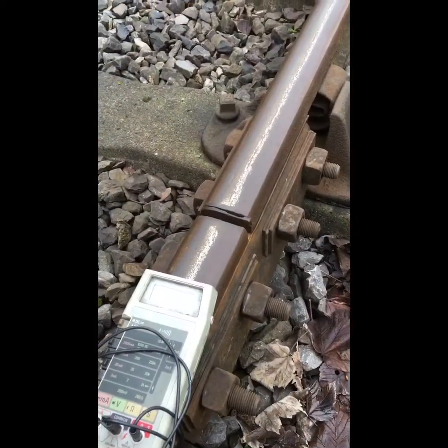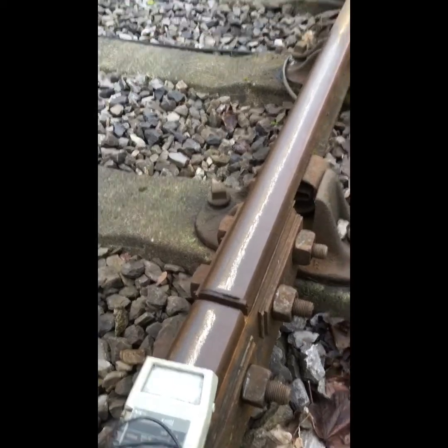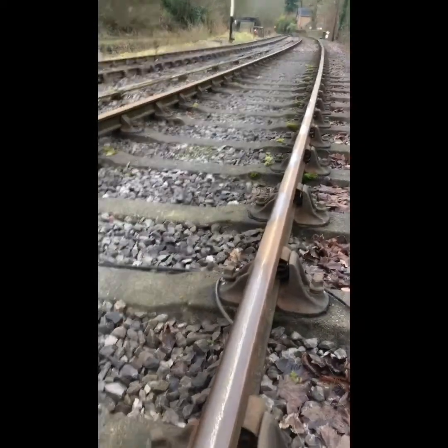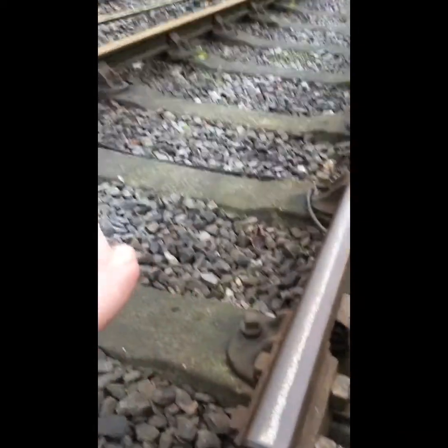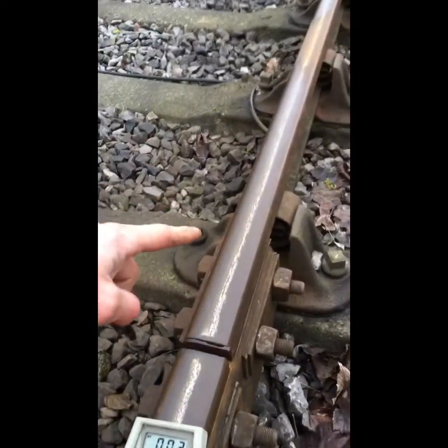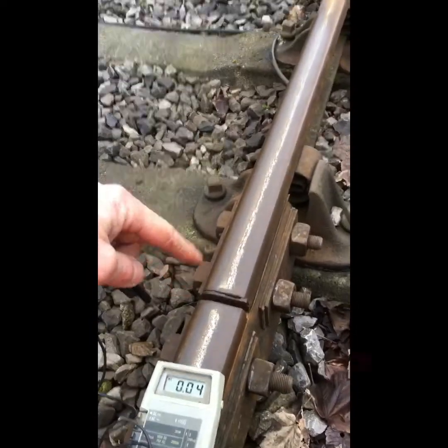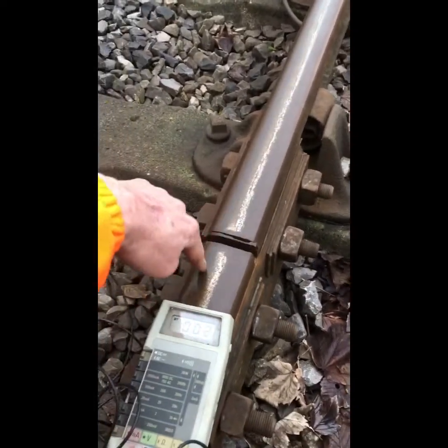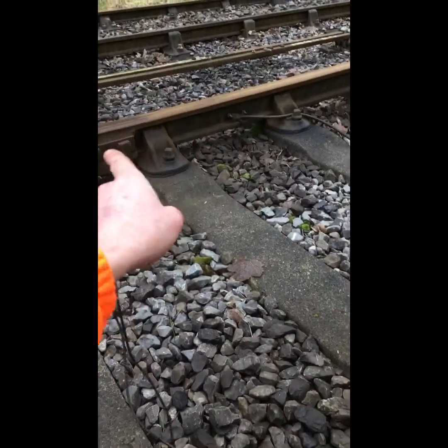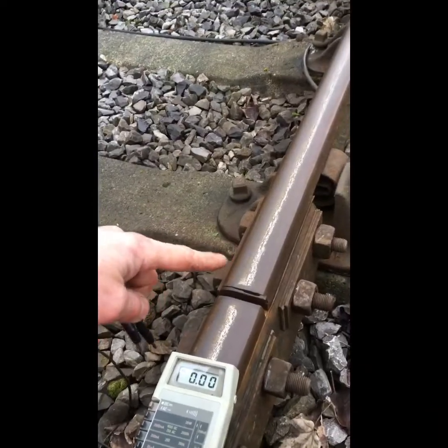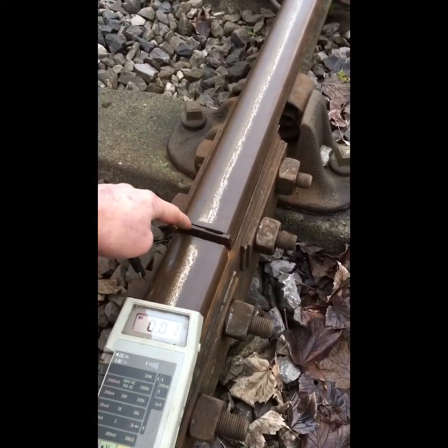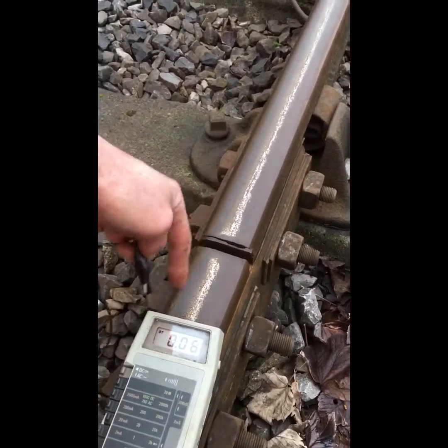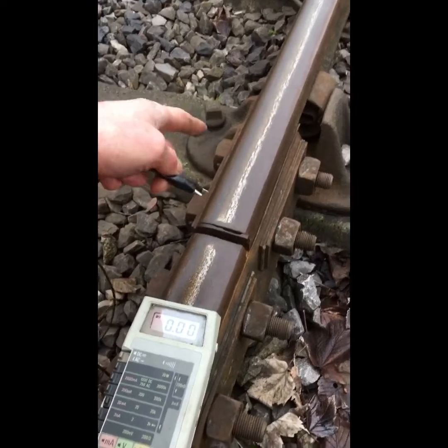Now, one of the important things to talk about with track circuits is track circuit stagger. For instance, if this was the positive leg and that was the negative leg, we would design our next adjacent track circuit to have opposite polarities. So the positive would go to a negative, negative would go to a positive. Thereby, if there was a fault or a failure of the insulated block joint, it would drop the tracks, and we'd be able to know there's a problem then.